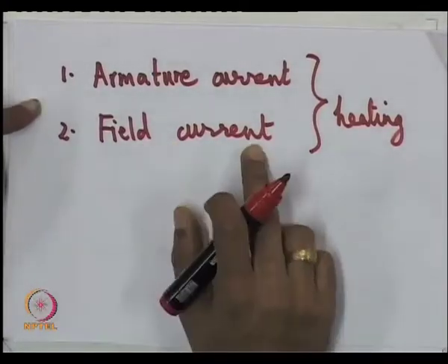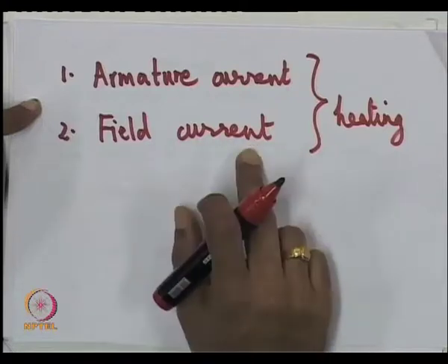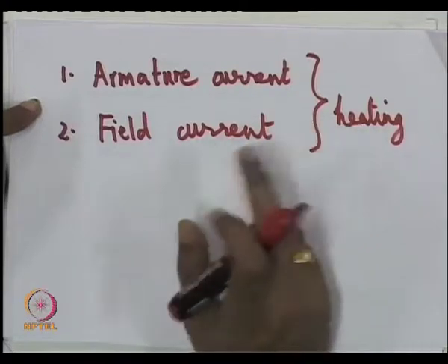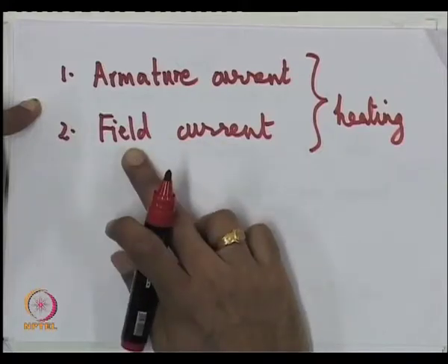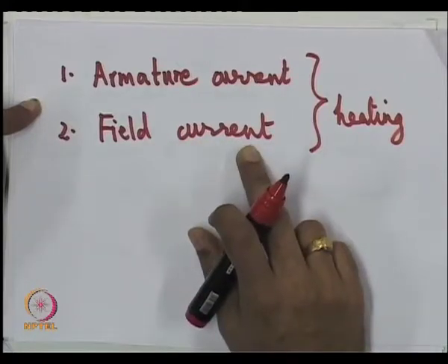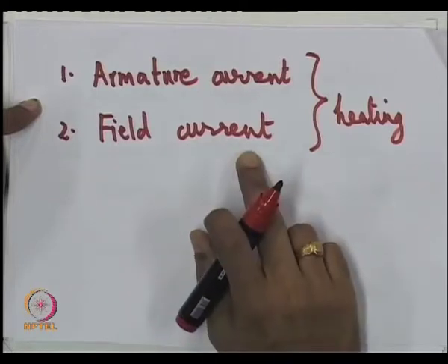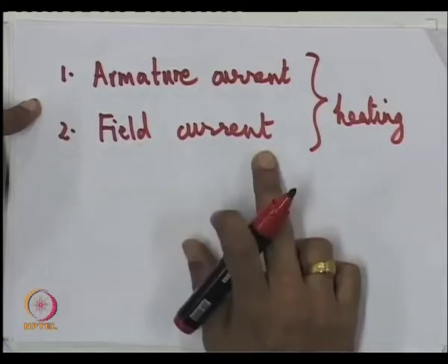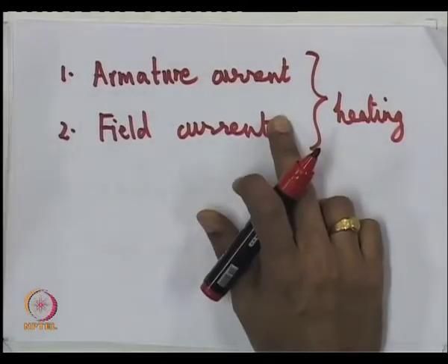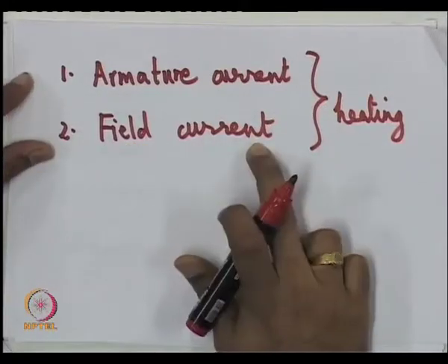Now, the field current limit also prevents you from increasing the Q beyond a certain point. Remember, in a synchronous machine, by changing the field current, you can change the reactive power, but you cannot go on increasing the reactive power. After a point, you will find that the field current hits its limit. So, even though you have very low real power, you cannot have Q very high, because for that you require very high field current.